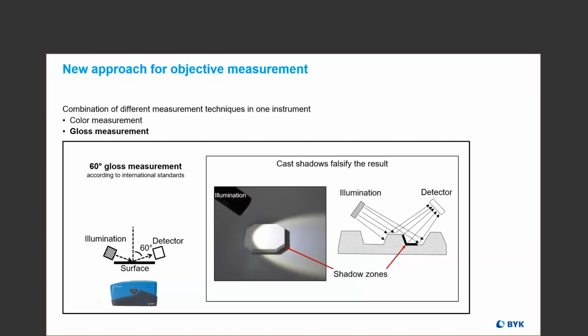And some of that light, when it hits the surface, is going to be diffused, just meaning it reflects off in all directions. It's deviated to all directions rather than reflecting right off at that specular angle. So glossy surfaces have a high specular reflection and a low diffuse reflection, and low gloss surfaces have a high diffuse reflection and a low specular reflection. So the gloss meter's job is to measure the specular reflection off the surface, which is a direct indicator of how glossy the surface will look. So higher specular reflection equals glossier surface.